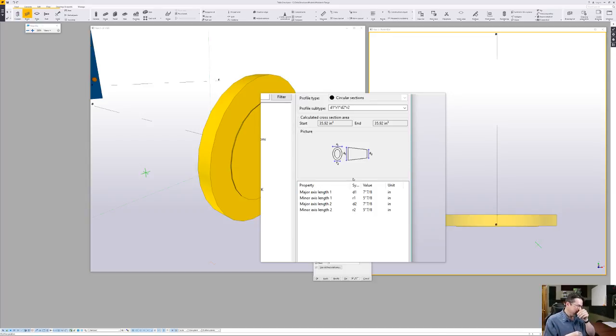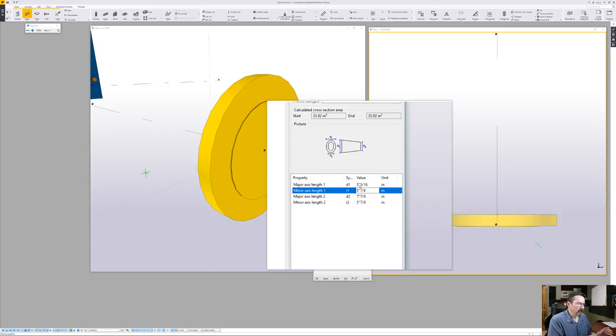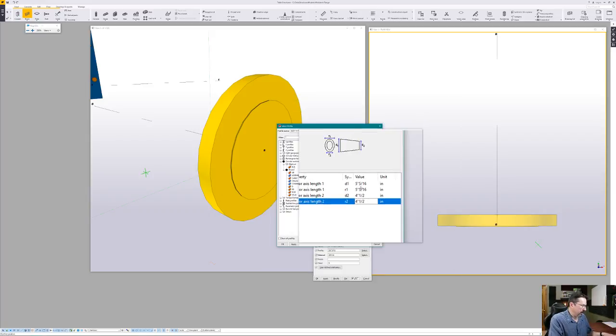All right, so for our D1, we're going to put in the actual diameter of what it was, the decimal, so 5.31 inches. And you're going to see it switch over to what it rounds up to for the U.S. Imperial. And then I'm going to put in the same dimension for the R1. And then R2 and D2 here are both 4.5 inches. And that now has our parts set up.